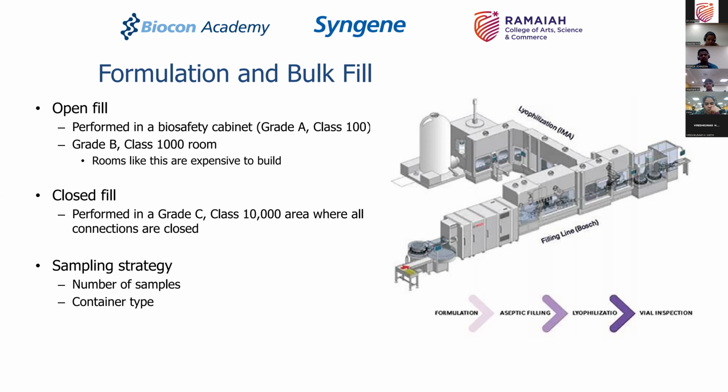In all the cases, the filling operations remain very similar: either you use ready-to-use pre-filled syringes, or you subject the pre-filled syringes or cartridges, which are already siliconized, or you may even inline siliconize them. So you will wash them, you will siliconize them, you will wash them again, you will depyrogenate them, you will do the filling.